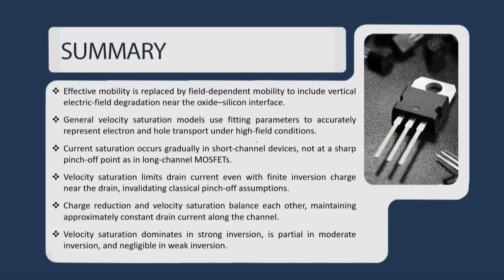So, let me summarize here that we have seen the velocity saturation effect is a very important short channel effect, which we need to consider in our model. When we incorporate the velocity saturation, the current equation can be given as Idsn divided by 1 plus Vds divided by Ec into L. Later we said that this approach is not that good because it causes a convergence issue in simple CAD tools.